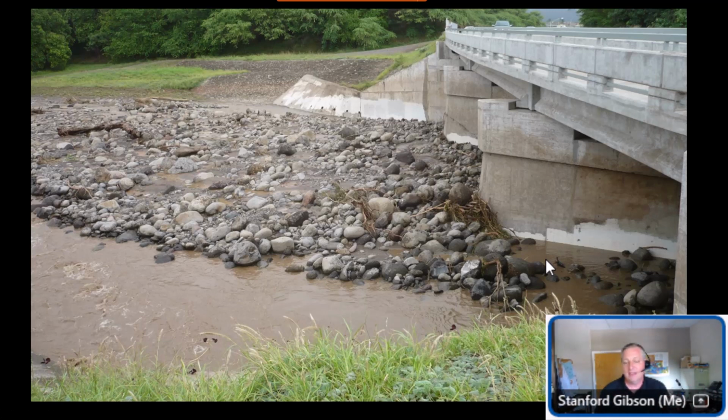And so now I'm thinking the 2D model is just wrong, that I should trust the combination of 1D and experience. But there's another line of evidence that we just don't take into account enough, and that's local experts. And so there is a team of guys out there that move this sediment around. And so I just talked to them and I said, listen, my model says that we should be depositing in the right bank. And when I look at this, it's all in the middle and the left. And they're like, oh yeah, it always deposits in the right bank. We just got in there with our bulldozers and moved it over to stage it.